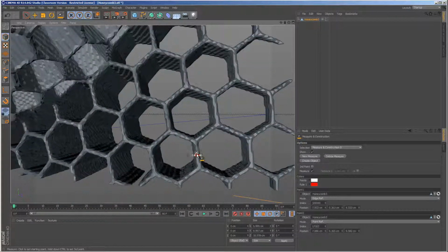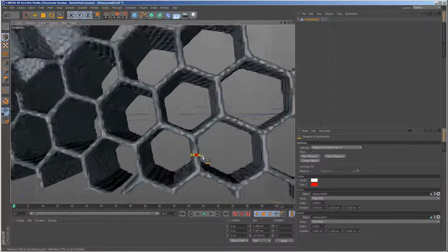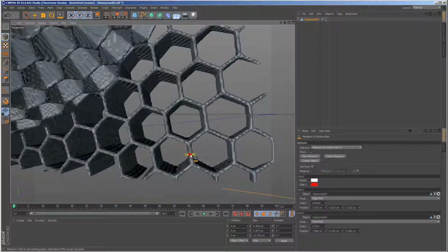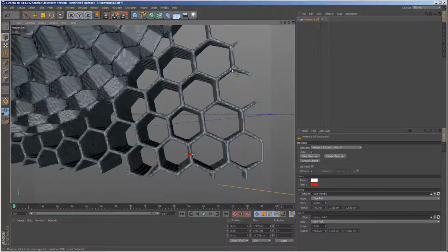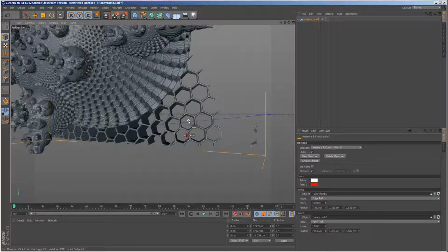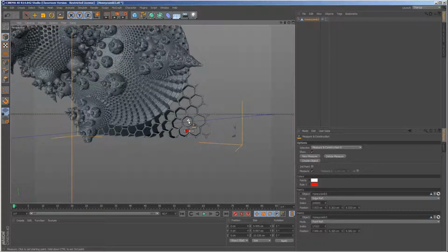So we need this to be like 3/10 of a millimeter, or 3 millimeters, or 2 millimeters for this. This would be considered a supported wall, so this should be 2 millimeters. So we're well below that, and especially these little points that come out here will be way too small. So that's a way to measure.